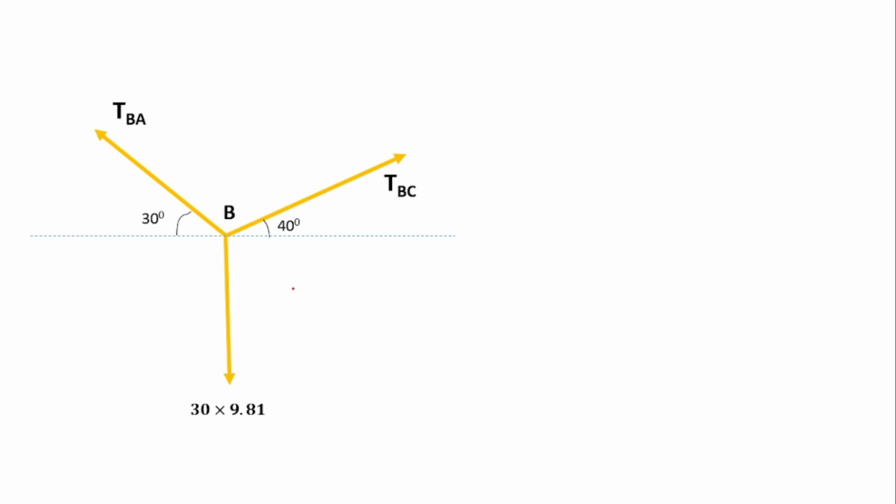Now we'll see whether it satisfies Lami's theorem or not. The system is in equilibrium, and it consists of only three forces. All the forces have the same direction outward, so it is a concurrent force system. So it satisfies Lami's theorem, and here we can easily apply Lami's theorem.